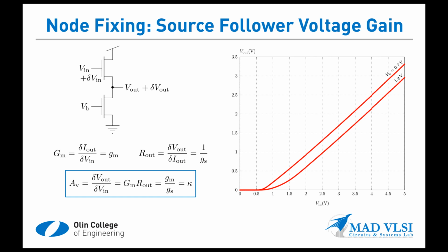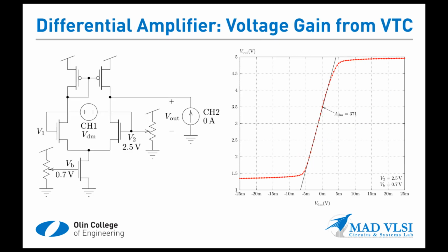I also want to show you another example, and this actually is something you'll be doing in Lab 8 in the second experiment. So this is our 5-transistor diff amp, and this is some actual experimental data that I took for this presentation on this particular circuit, which I actually made from some ALD1106s and 1107s, and I measured these data using one of the SMUs from the class. So this is precisely the kind of thing that you'll be doing in simulation in Lab 8.